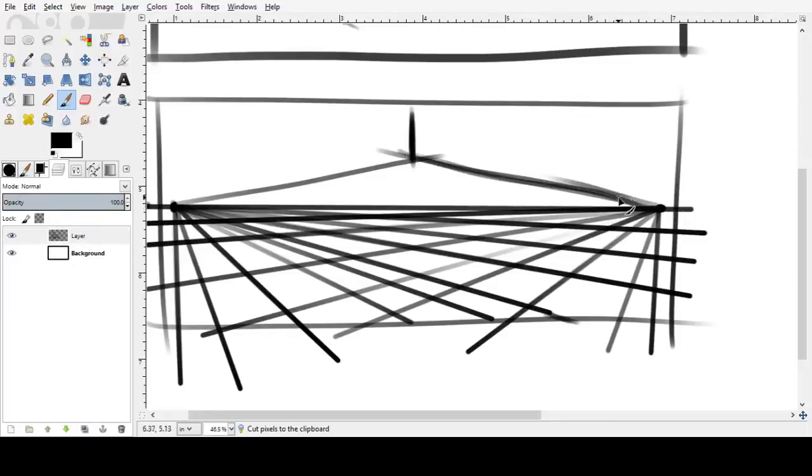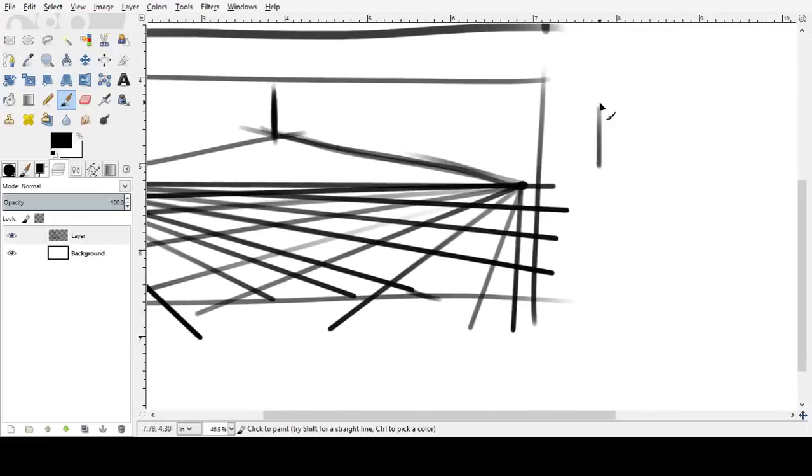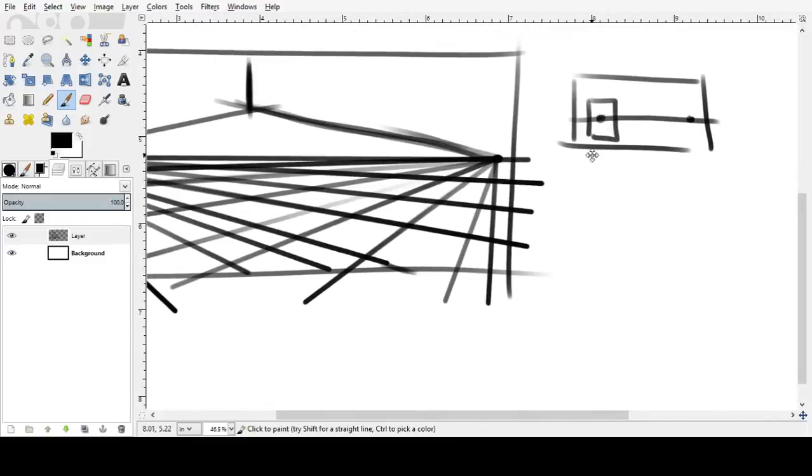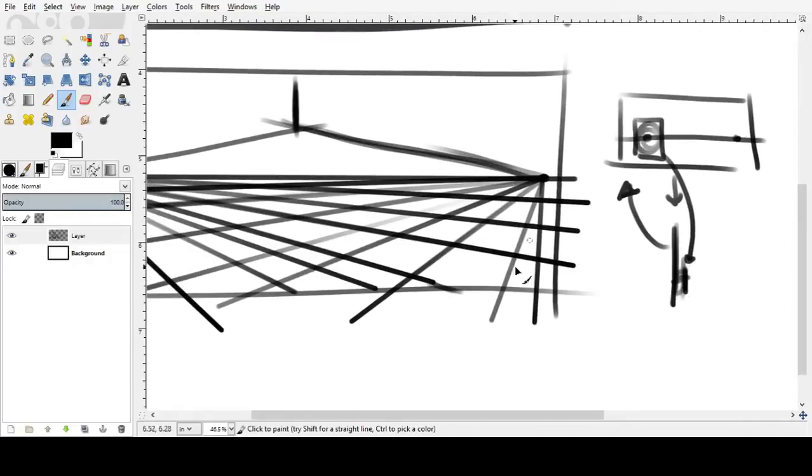What happens in 2 point perspective, where in 1 point perspective, I'll show you a little bit over here, you have a whole front that's flat. Like if we were looking at this from a top view, this would be the picture plane, and this would be the box right here. This whole side is flat and parallel to the picture plane.